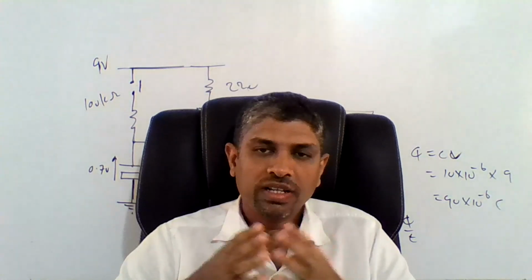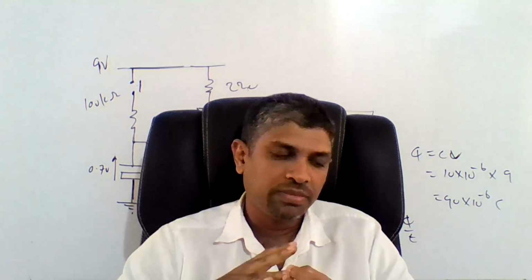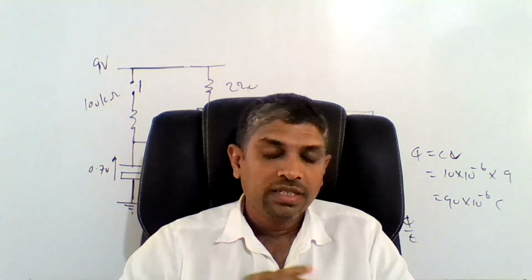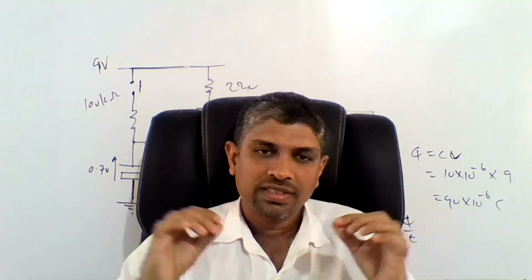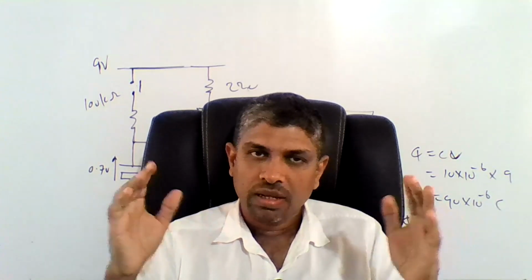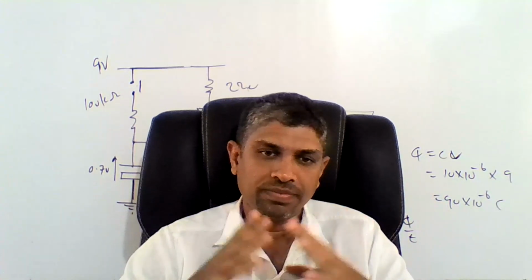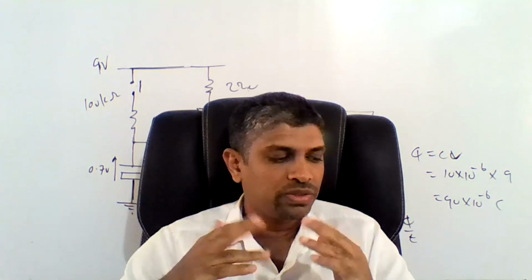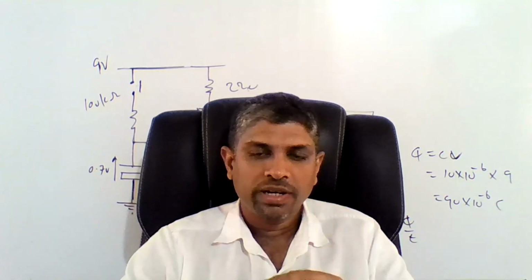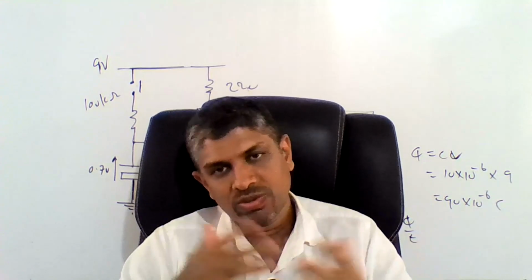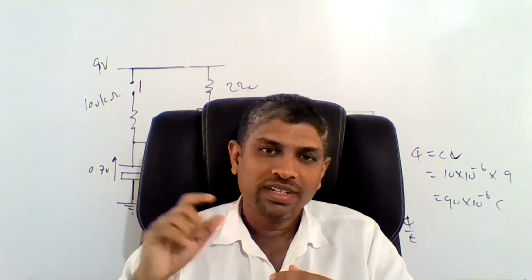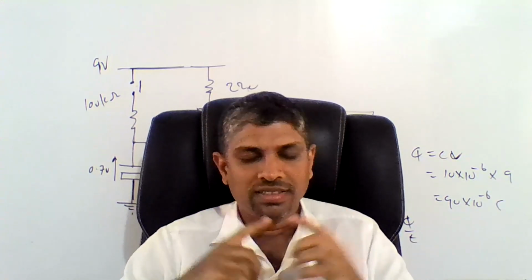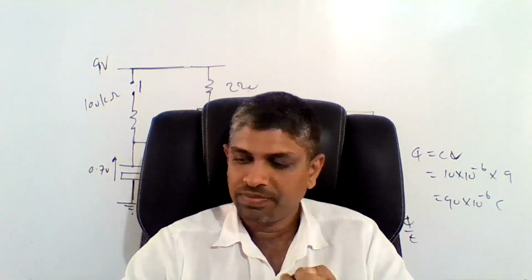You can build it and try. In your case you have to use either a 10 microfarad capacitor or a 100 microfarad capacitor. You can remember that when two capacitors are in series, capacitance is reduced. When the two capacitors are in parallel, capacitance is increased. So you can use two 10 microfarad capacitors, connect them in parallel, and visualize this. Okay, try it and see.